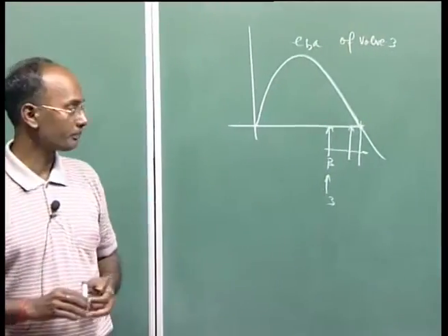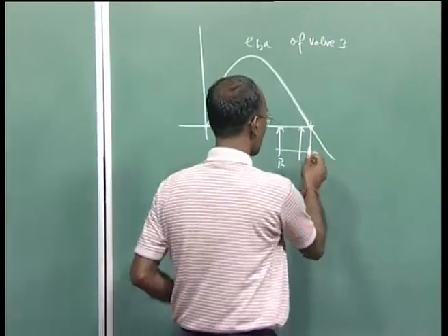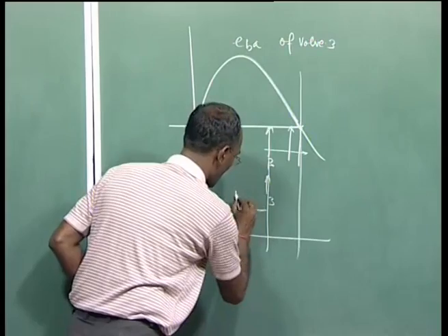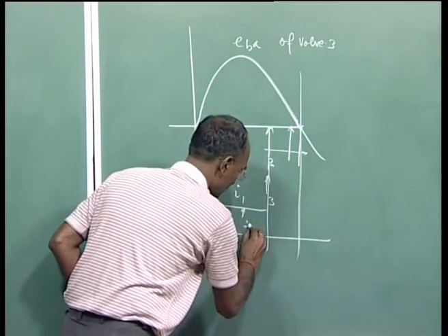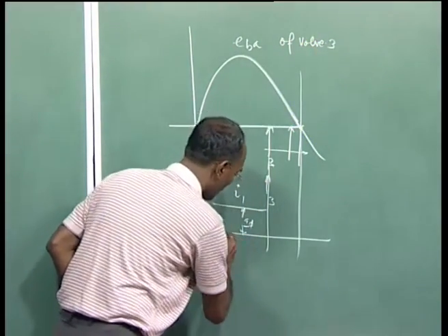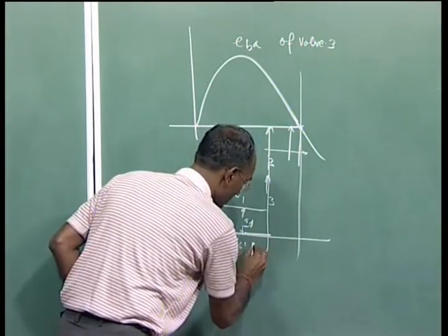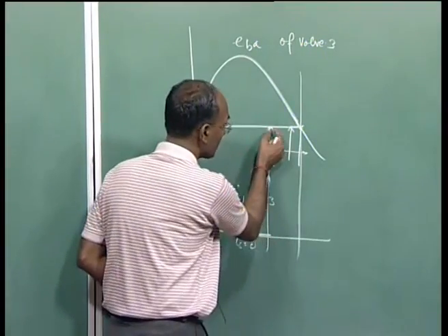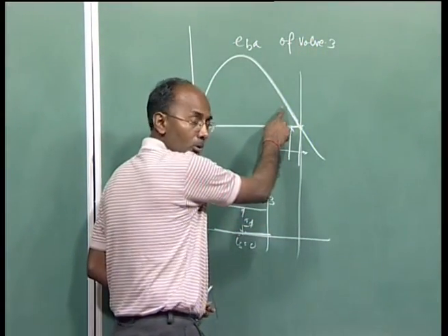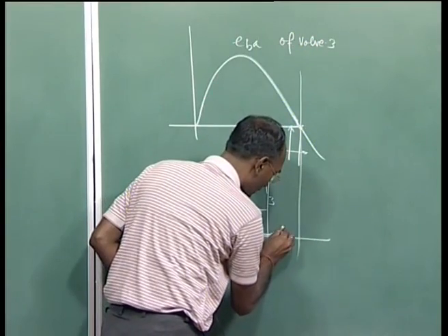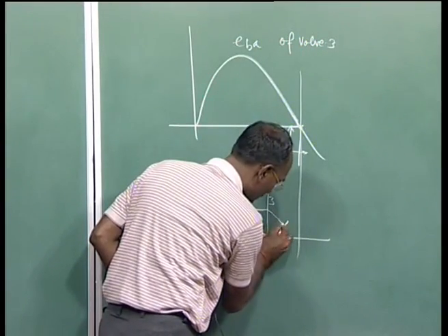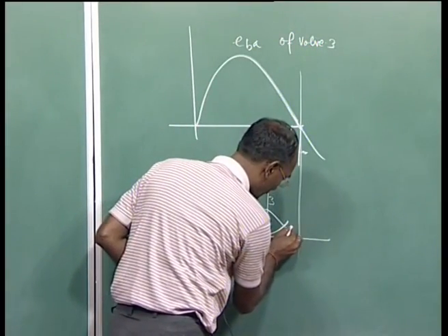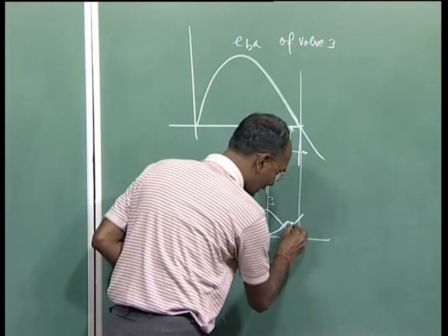Here, if you draw the current, let us suppose this is your I1 current, which was Id here, and your I3 was 0 here. Now the commutation is starting. Because valve 3 is fired and the voltage is positive, its current will increase here and this one will decrease. Now, there is a possibility that even though it is coming here, it again comes back, and the current taken over goes back here again.